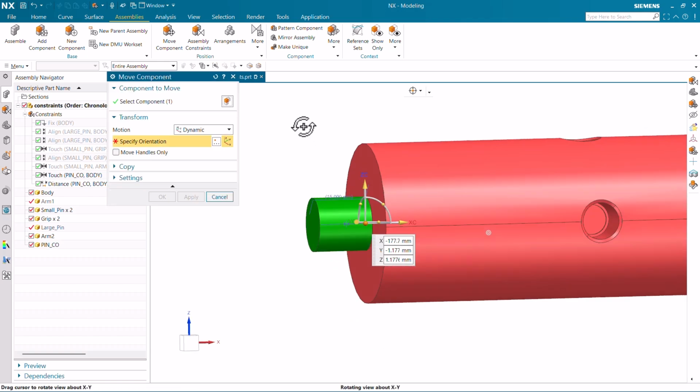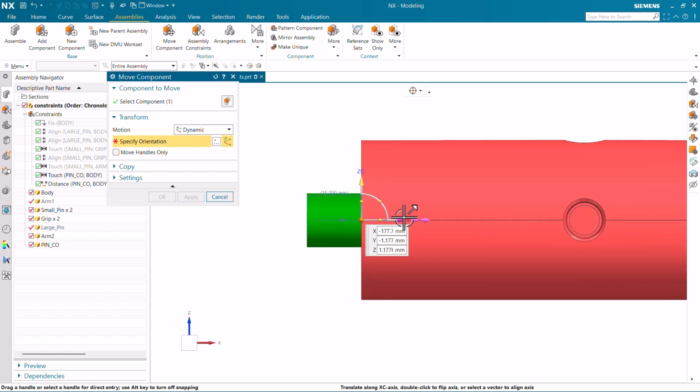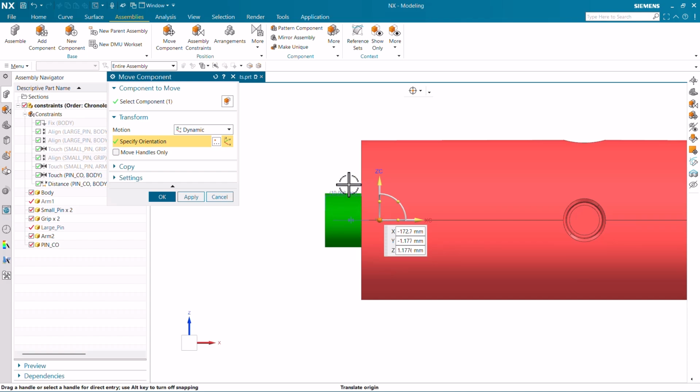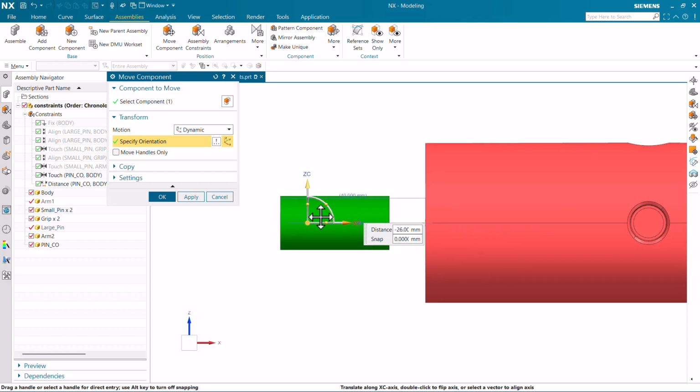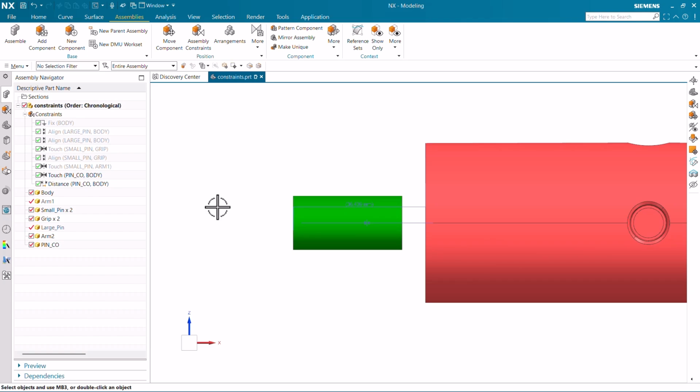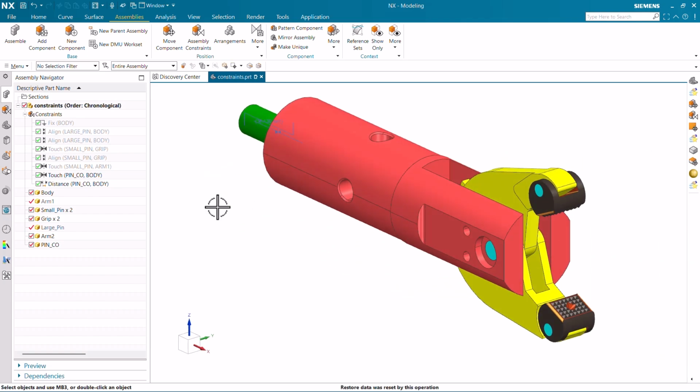Now we have a limit here. We have a limit from 10 to 40. Now you can see this can cover up to only 10, and if I go beyond this, it is not allowing the part to get moved. And here if we move in this direction, this is 40. So this is how we use the limits. Basically the limits get used in arrangements where we want to show the conditions of open and close. So this is something which is the advanced part of the distance.